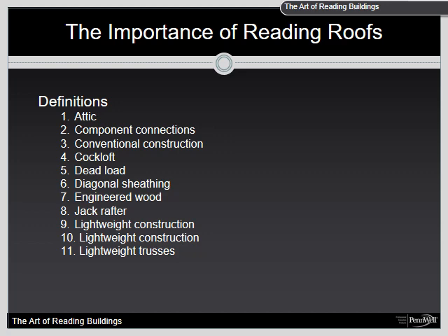Next definition, component connections, also known as framing junctions, where 2 or more structural members are joined, and for this chapter, how they are joined. As an example, a connection can be secured by nails, bolts, steel plates and bolts, metal finger joints, gusset plates, and other means. The way structural members are joined can determine how long the connection will last under fire conditions.